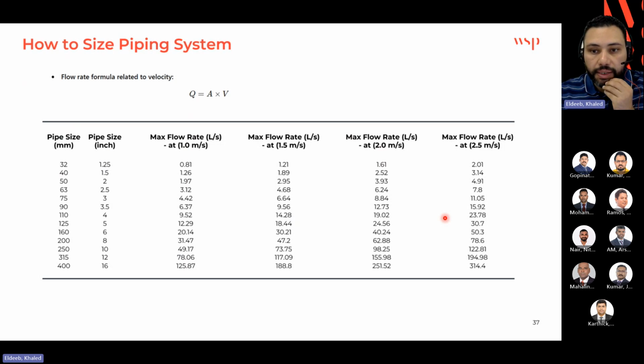And I need you to know that this table is for rough sizing only, because the accurate sizing shall be done based on the actual pipe diameter and the pressure drop in this actual pipe material and the allowable pressure drop in this material, and so on. So there are many other factors that could be considered in order to calculate the diameter precisely.